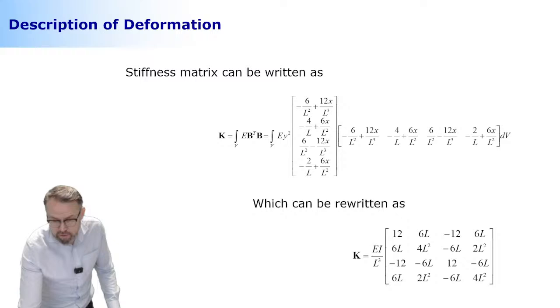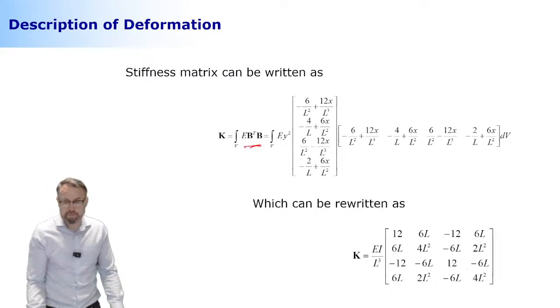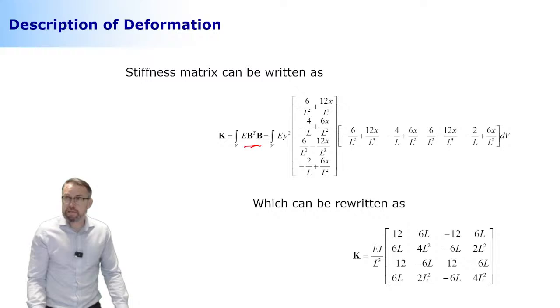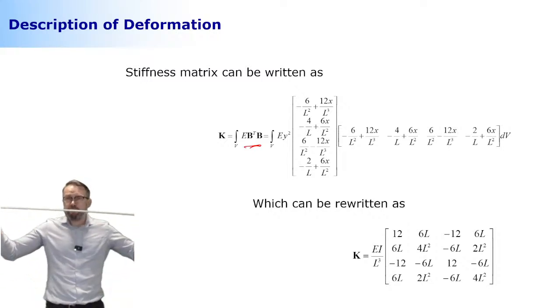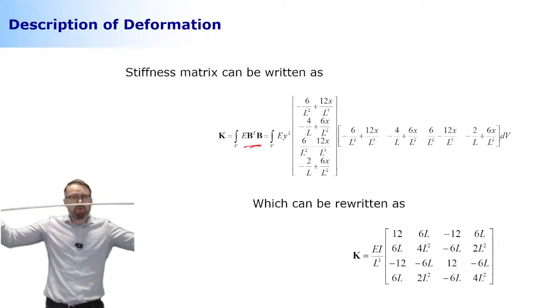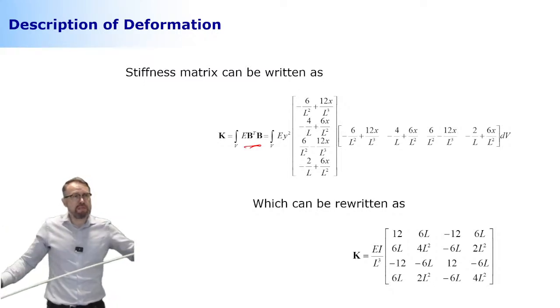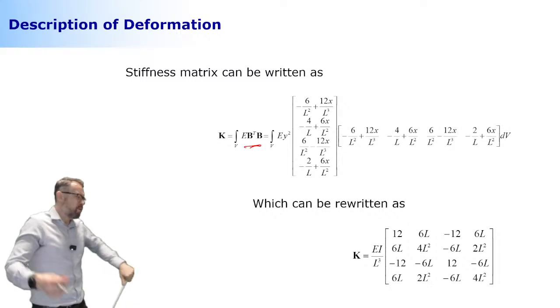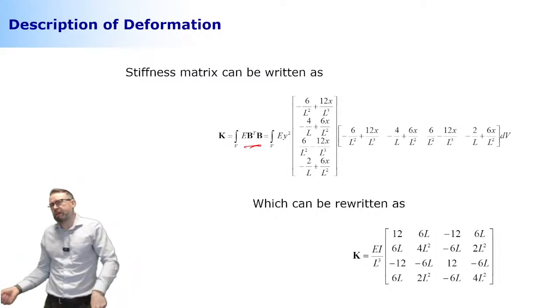And now with the help of your kinematic matrix, you can build your stiffness matrix. The stiffness matrix is telling you how much the element is resisting the forces, if there is a force, in each of the degrees of freedom associated with nodes. So that's what the stiffness matrix is. I understand where the typical teaching comes from, that it's like a spring.